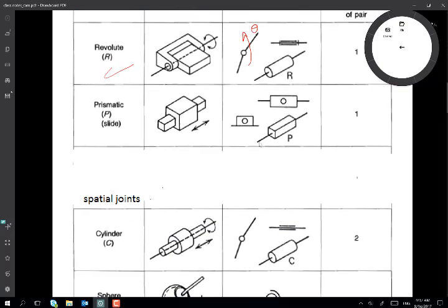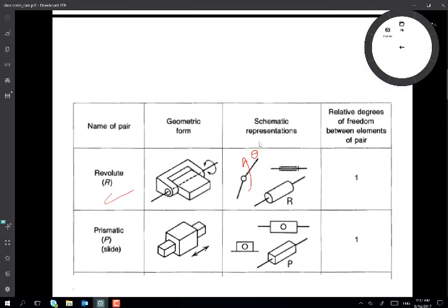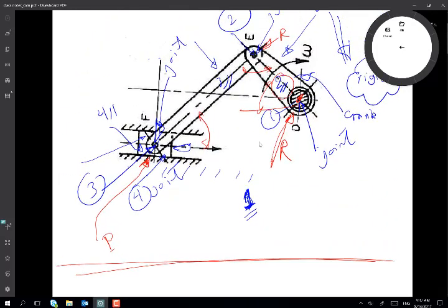Now just let me say that this specific linkage, before I leave this bit here, if we look at it, we'll find that every point on the linkage actually moves parallel to a specific plane. We can project everything to a plane behind the linkage, and everything will be projected with its own proper dimension. There's no angle between any link and the specific plane behind the linkage. So everything can be just projected, right?